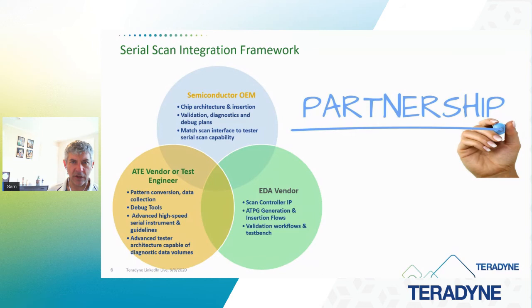And then it's also very important today. Another thing that's happening with scan is we see a lot of data collection happening in terms of scan map failures. And sometimes this is used for advanced binning workflows. Sometimes this is used for advanced fault analysis and debug workflows. But the tester architecture has to support a lot of data passing. And our current generation UltraFlex Plus platform has a tremendous bandwidth at the tester. And so that's something that's been helpful in that regard.